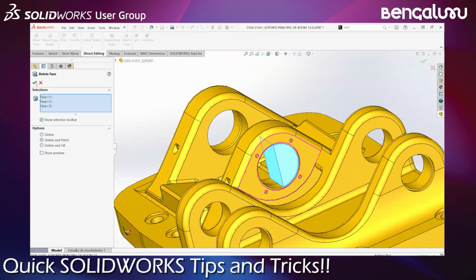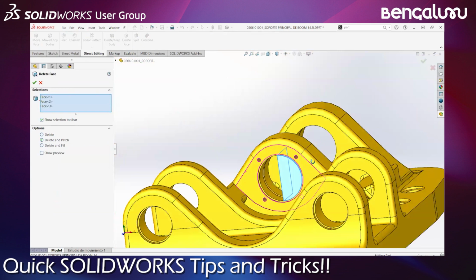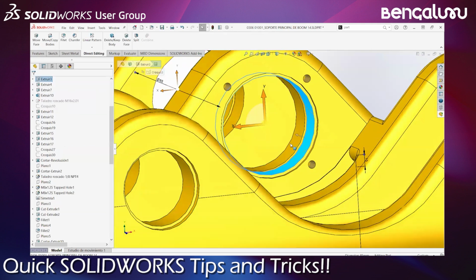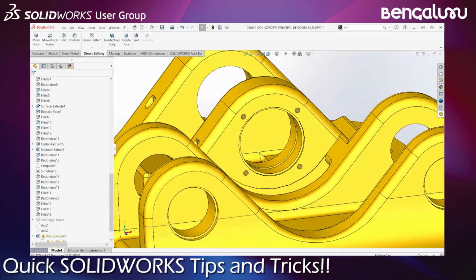And you have this delete and patch command. Once you say delete and patch, SolidWorks not just removes this face, but also patches it. It understands the geometry of this circle and patches it neatly. This saves you the time of drawing a circle, cutting, extruding. All of that is taken care of just by this delete face.